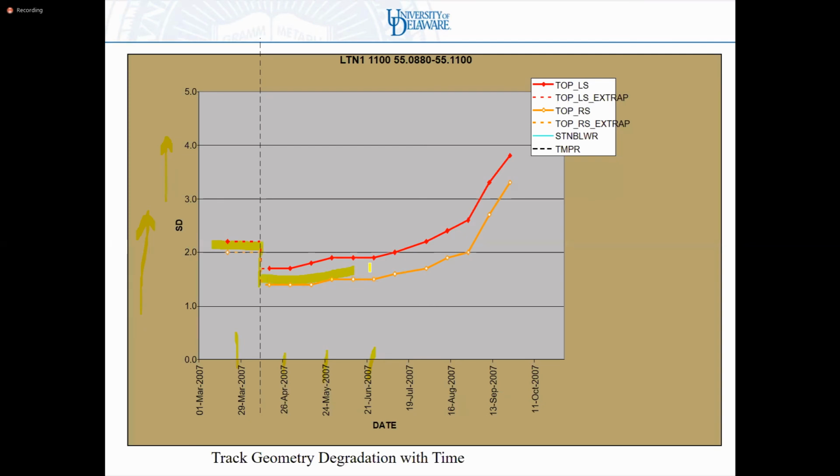And then I start looking at my rate of degradation, and you notice it's nonlinear. So right away, a simple linear projection may not work that well. In fact, if I take a simpler linear projection over here, it would tell me I won't have a problem to wait out here, where in fact, in reality, I'm coming right up here. If my standard deviation limit was 4 here, a linear projection would tell me I've got another 6 months to go, whereas the reality tells me I don't. So this is a projection forward. This is how standard deviations can be plotted.